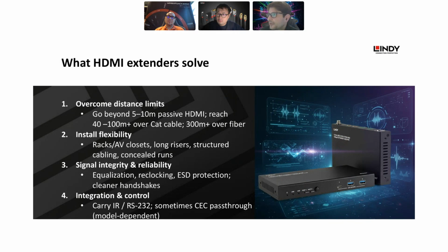Second, install flexibility: racks, AV closets, long risers, structured cabling, concealed runs. Third, signal integrity and reliability: equalization, reclocking, ESD protection, cleaner handshakes. And integration and control that this kind of technology allows: carrying IR, serial control RS-232, sometimes CEC, pass-through, depending on the model that you are using.